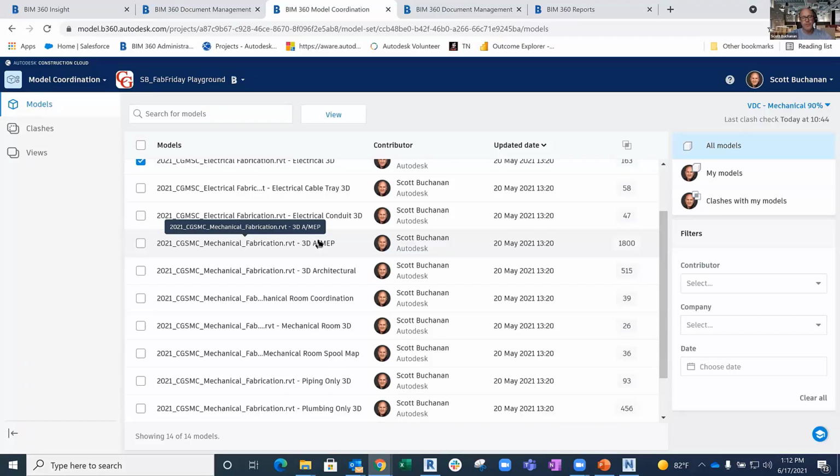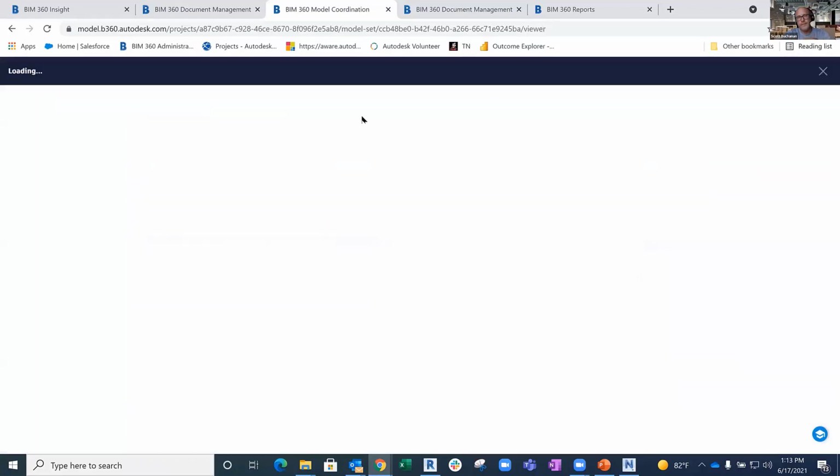I do in the live one, but just not this one. So you'd be exporting out those individual NWCs and then aggregating those inside of Navisworks. Whereas inside of model coordination, it's taking those 3D views from your publish and automatically extracting them out, right? So I get to choose what views I want to pull, or again, have that aggregate behavior to it.